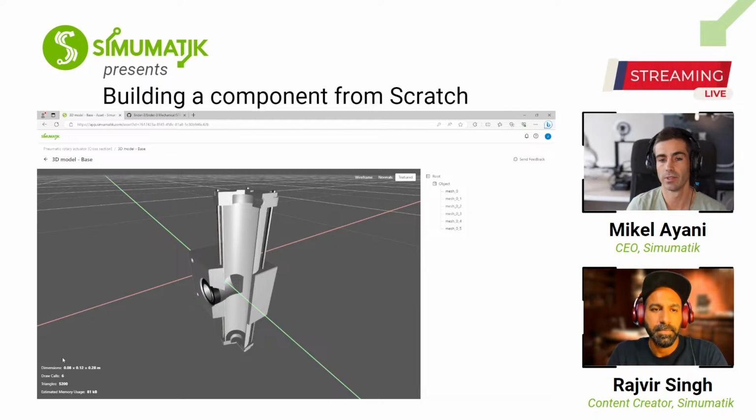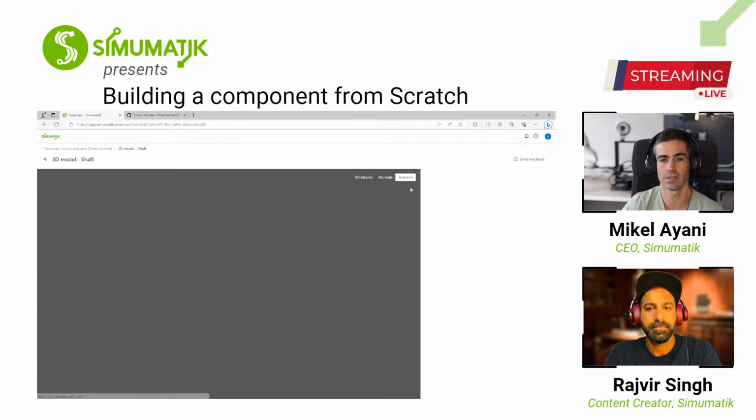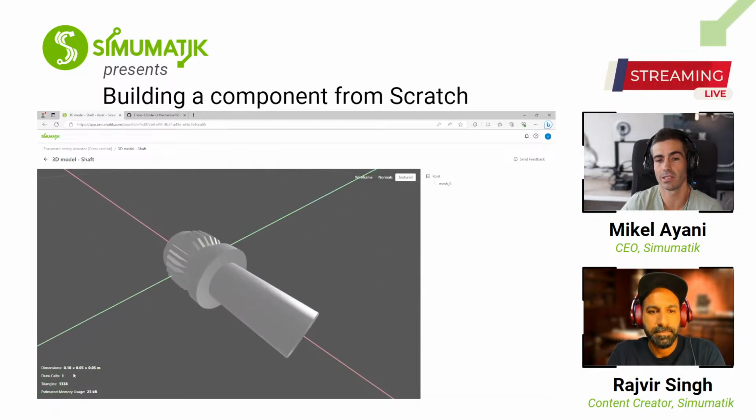Okay. So in this case, do you have any recommendation range? How much should the draw calls be? Yeah. Which is good, if you can have just one, that's the best. And we will see that we can get to that with some extra feature we have now in Simumatik. But in this case, it is 6 draw calls. Okay. And if we open another component, we will see that in this case, this is just a draw call.